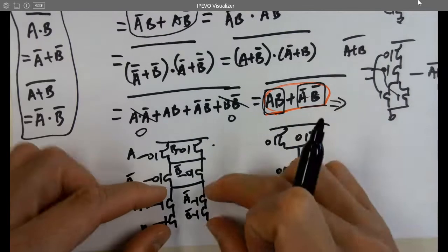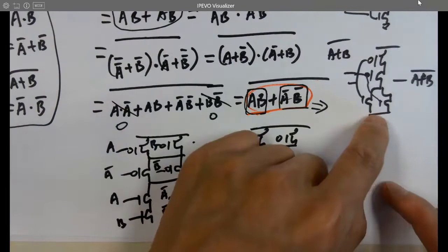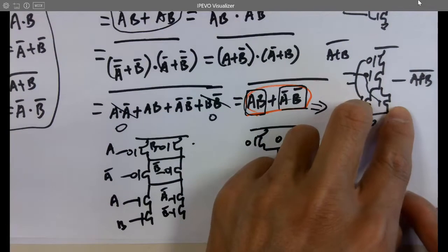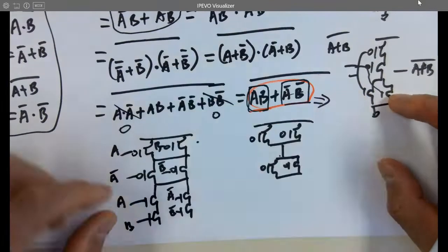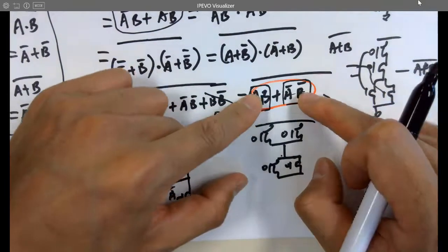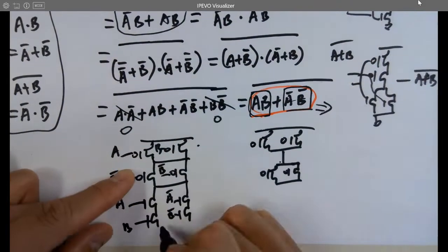And I put these two in parallel because this is NOR gate logic. Remember the NOR gate for the NMOS, they're in parallel. The two entities are in parallel. So these are the two entities in parallel, right? That's ground.